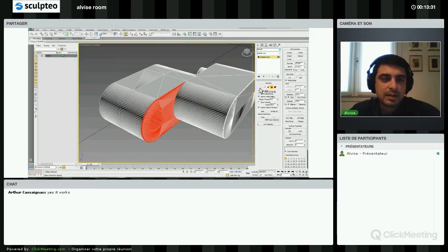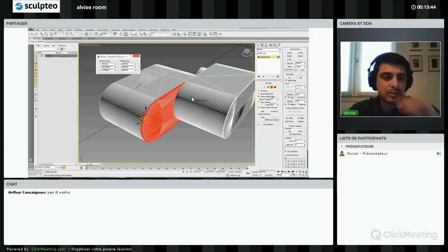I right click it and this window opens where I can set the precise dimension. The one to move is the X axis, and now it's set to minus 4.1. So just a test calculation: I want to move it 0.4 further, so this number has to come down to 3.7, and press enter, and the face moves. So this part is done.